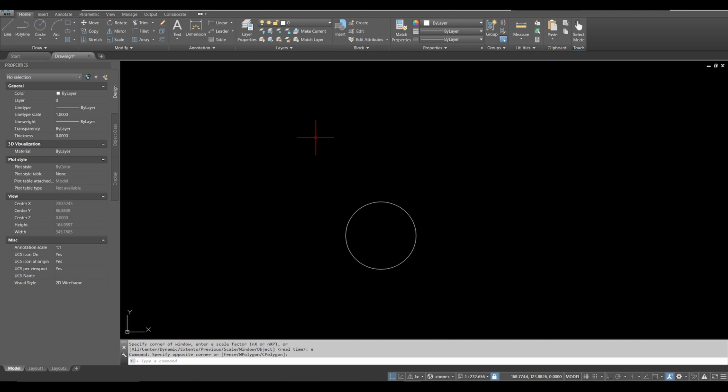And, you know, hopefully we can come away with some more practical skills and actually get a feel for how to create entities inside of AutoCAD. So first off, we have the line and polyline commands, and I want to just be clear here. While I'm highlighting these on the ribbon so that you can have a visual of them, almost never, and there are some exceptions, will I actually come up here and click on a ribbon button, because it is, in a professional environment, extraordinarily slow. No one does it. Well, nobody good does it. I'll say that. For most of what you do, you want to be using the hotkeys.